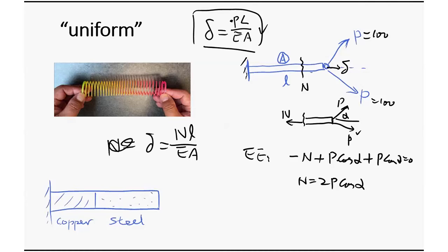For example, I can give you one quick example. Say I have a cable here, and I have this wheel here, and then I apply moment M here. So I'm trying to apply this moment to twist this wheel to pull on the cable. In this case, there's no force, there's only moment. Then how do you determine it? You still do the same. You cut it here, determine the internal force N, and that's the one you use in the equation. So that's why I say it's the internal force you use in the equation.